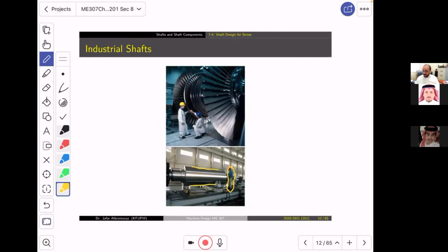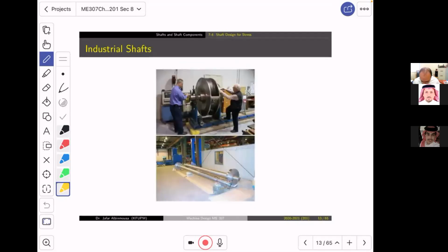And probably the reason why, you know it, right, is deflection. It's probably very safe in terms of fatigue. But as we told you, if you're going to make it from steel, which is the best material, you will end up only controlling the deflection by increasing the geometry, although it may not be necessary in terms of fatigue or yielding.